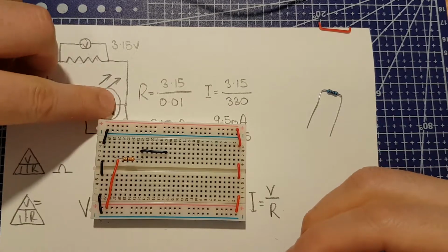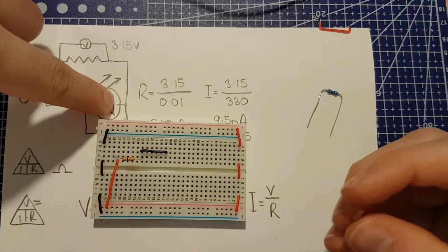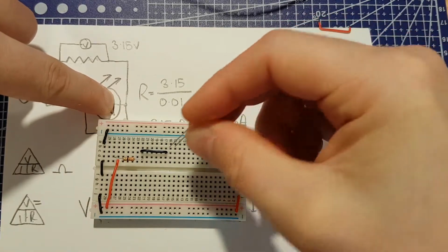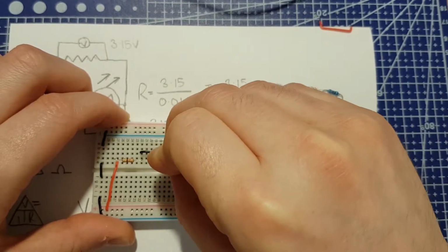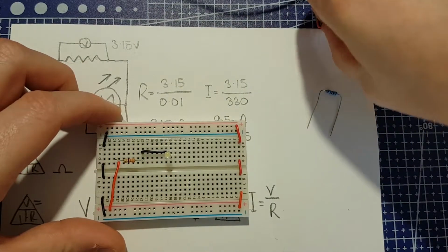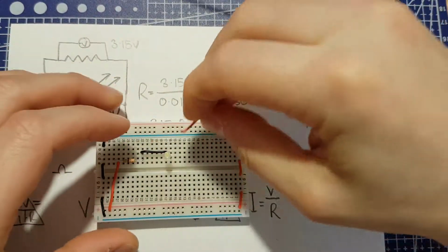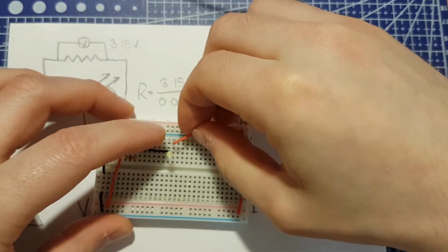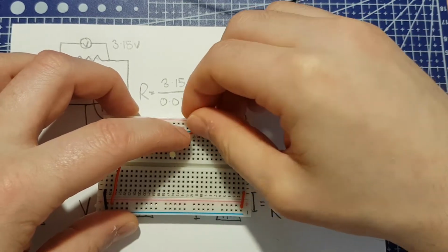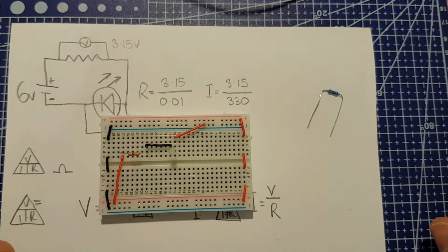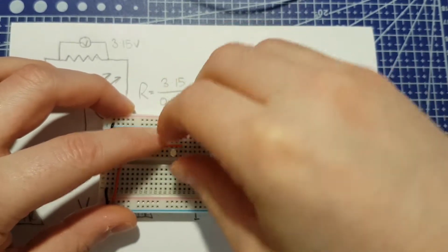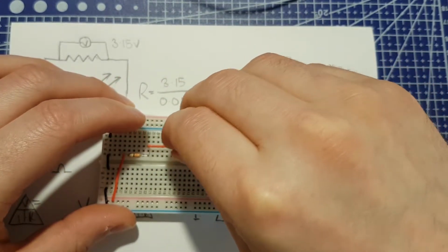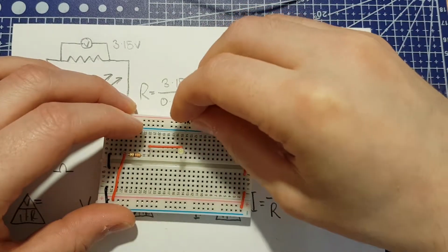Then I'm going to go into the anode, which is the positive end of the LED, the long leg of the LED, and the short leg of the LED, which is the cathode, the negative leg. I'm going to take our jumper cable and go from the negative up to negative of the breadboard. In fact, I am going to swap these wires to make it easier for you to remember which end is going into the negative and which into the positive. There we go, that's a bit better.